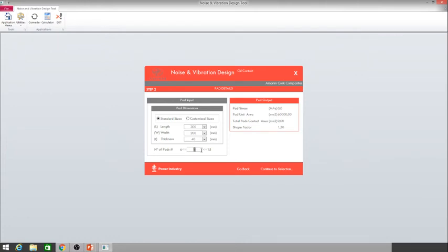So using 6 doesn't make much sense. We have 2 options: 7 and 14. You didn't see the length, but the length of the legs is more than 900 millimeters. So we could opt to use 7 or 14, but in 900 millimeters, using a length of 300, 1/3, this system will not be stable. So the best option will be using 14.